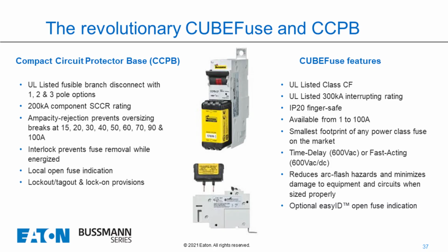So when the fuse does open up, if you see right below the handle, there's a little dot to the right. If the light lights up, that means the fuse is opened and you need to change the fuse out. But OSHA requires us to make sure that we check to find out why the fuse opened, and then we'll replace the fuse. Just like when a breaker opens up, to reset it, we have to find out why it opened up, and then we can reset it.